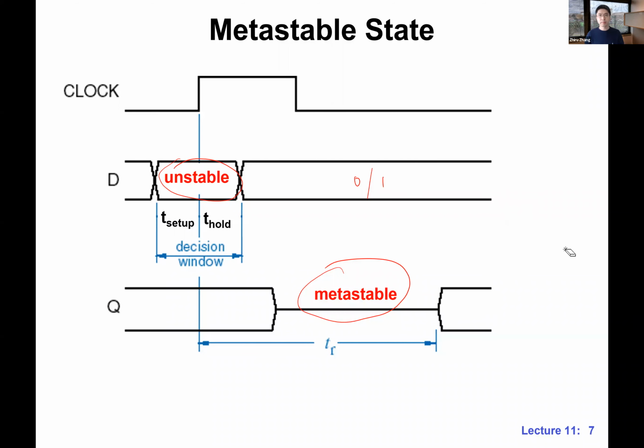Also, last time we talked about glitches. This is another review. I just want to make sure that everyone still gets the intuition. We talk about the 2-input mux, this is a 2-to-1 mux. This one may have some glitch. If you look at the waveform, initially over here X and Y are both steady, they are ones. Since they are steady, there's supposed to be no glitches, since this is a mux, so it doesn't really matter whether S is 0 or 1. F, the output, is supposed to be 1. But somehow, if you look at this diagram, S is making a transition over here, from 1 to 0.